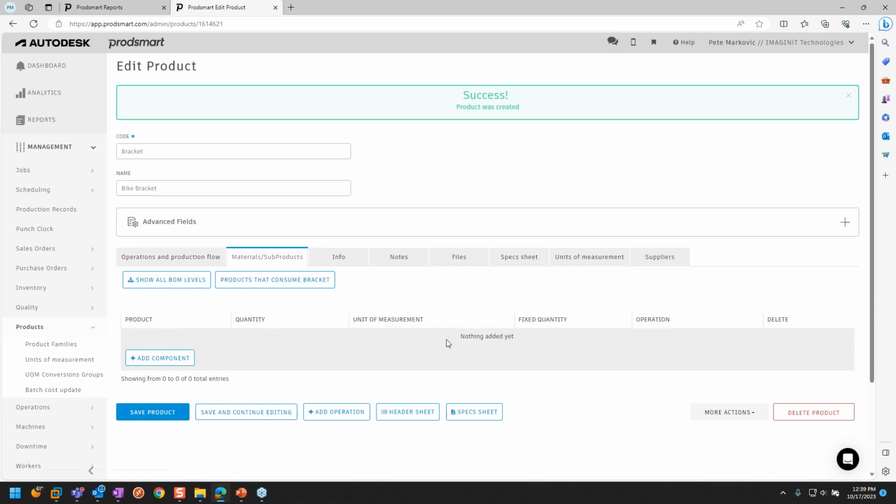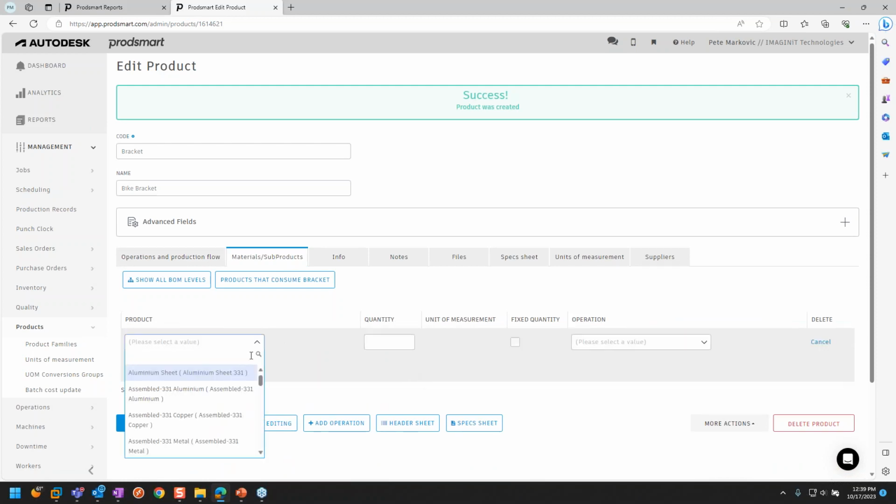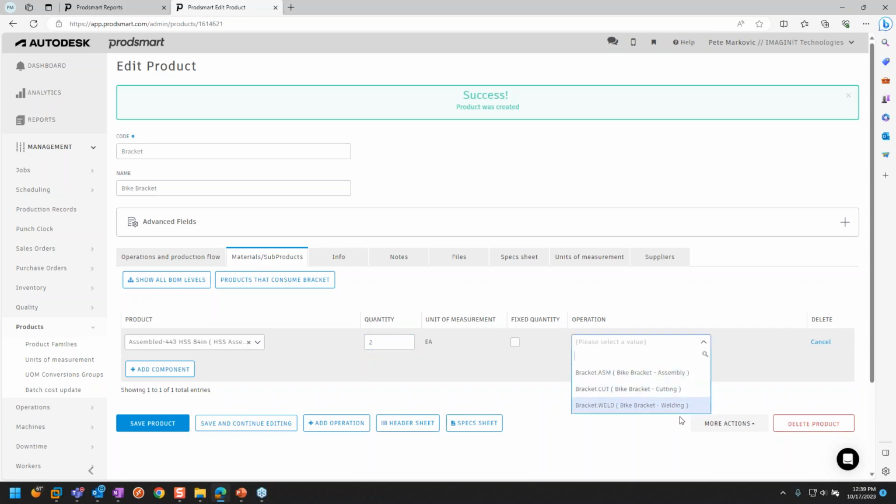Okay. Now, we could have also manually set up the operations for this product versus using a template. But once we have the product, we can now come in here and we can associate materials. So maybe there's a material that we need to use on this product. I don't know, I'm just going to grab something, not pay too much attention to what I'm grabbing, but let's just say I need that, right? How much of that do I need? Now the unit of measures, we can define that over in our raw materials area. So like maybe this should be in feet, but maybe in this case it's in inches, and we need 2 of these, right? And then for which part of the operation are we consuming that material? So in this case, it's the cutting operation. So we can even get down to that level of where are we consuming these materials for what, okay?